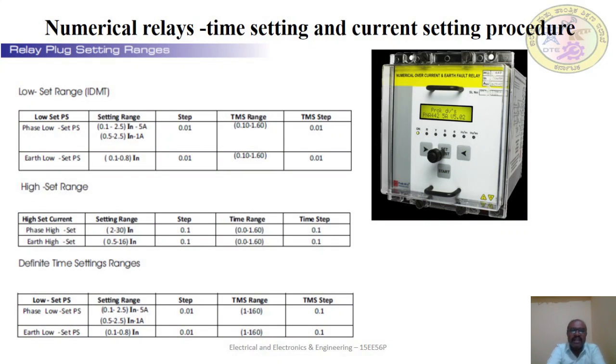The numerical relays evolved from the static and electromagnetic relays. They are basically devices used for measuring the electrical parameters in an electrical network and converting them into numerical data, which undergoes mathematical and logical analysis to decide on tripping of an electrical network. The main purpose of a numerical relay is to protect an electrical network from unexpected faults. These relays are preferred because of their versatile characteristics.